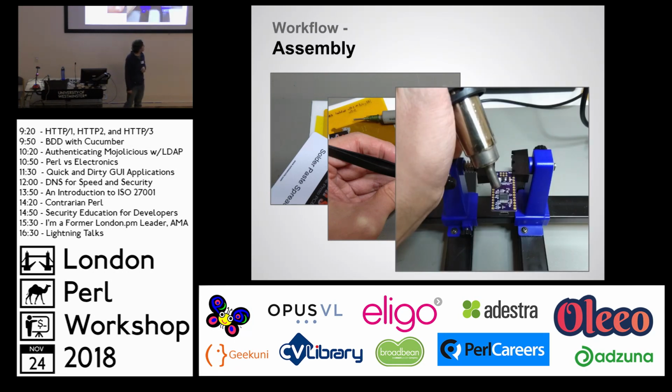And then you blow hot air onto it, and it melts the solder in a process that I always like to think is much similar to sticking the toppings onto a pizza with cheese. To the point that there are maker labs that do actually use pizza ovens for solder reflow, because it's basically the same process. You take your substrate, you put your reflow cheese on the top, and then you place all of your little toppings on the top, stick them in the oven, melts them, keeps them nicely stuck on there.